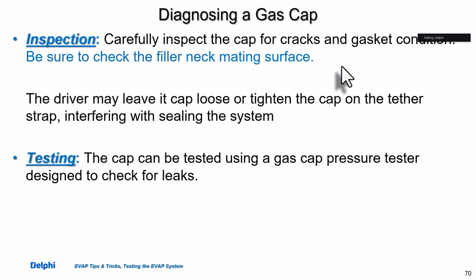Okay, the last few things on the check, the filler neck, don't forget that. Those filler necks take a lot of beating. Every time you put a nozzle in the car, it's being tipped down, it's being pressurized, being leaned on by the fill pump. Take a look at the filler neck, because sometimes your problem's right there. It's not the cap, but the filler neck is distorted.